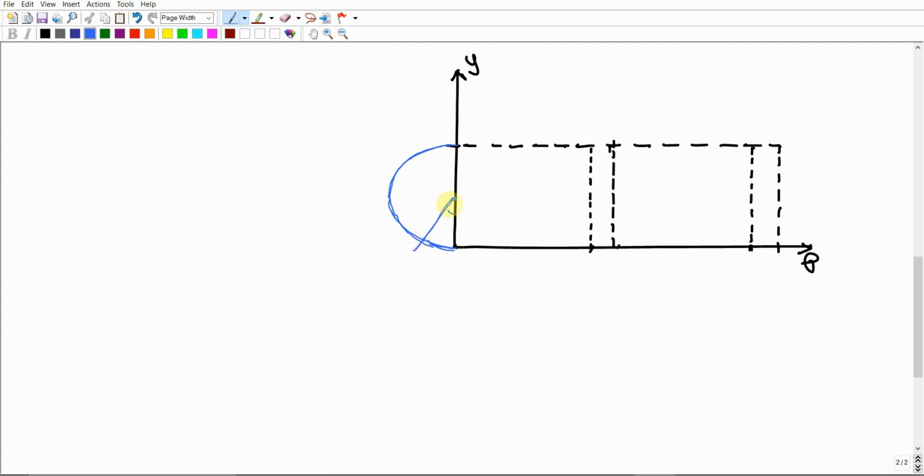Then you're just going to measure another 30 degrees, one more 30 degrees, to draw this second line. Make sense? Then you're going to end up with some points. This gives us point 1, and there is another point here; these are the points of intersection of the circle with these lines. If you draw a vertical line going up, you're going to intersect with the circle at another point on the other side. The same thing starting from this point: go up vertically, and this will intersect with the circle at another point.